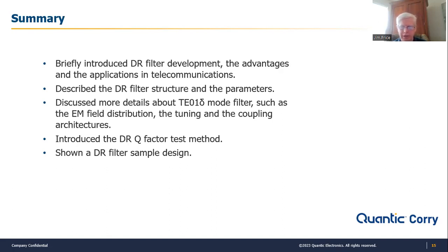The only downside is that you're only going to get a couple percent bandwidth out of it. So if you need a wide bandwidth, you're better off with the metal filters, because the dielectric resonator ones just don't couple enough energy from rod to rod or resonator to resonator to get you what you want. They're great for smaller size as well.